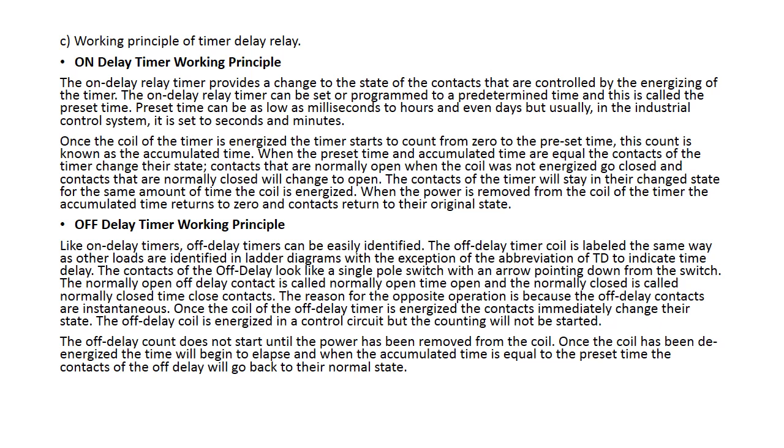So this one is for the working principle of timer delay. For the on delay, it provides a change to the state of contacts that are controlled by energizing the timer. So once the coil of the timer is energized, the timer starts to count from 0 to the set time. This count is known as the accumulated time. When the accumulated time is equal to the set time, the contact of the timer changes state.